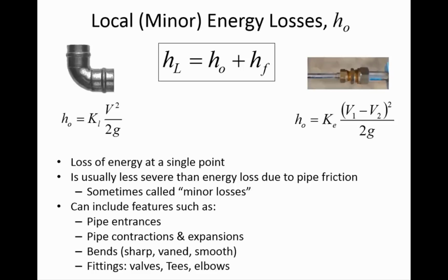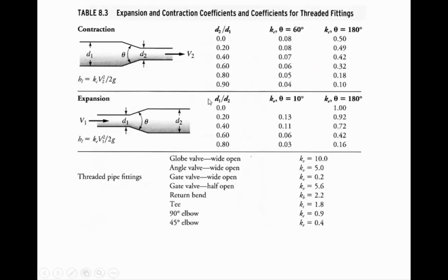And then the other thing you noticed here, in this one, it's saying 1. If you have the pipe exiting into a tank, then what that implies is that in that exit, you're losing 1 times the velocity head. That means all of the energy that's in velocity, when the water discharges into the tank, is just instantly lost.